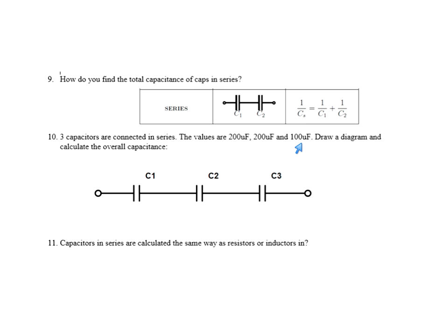But look at this. Here's how I would think about this. C1 and C2 are in series with each other, and they're both 200. If you do those two capacitors in series, that would give you 100. Two 200 microfarad caps in series would be 100. So these together are 100. Then you have another one in series with it, which is 100. So 100 in series with 100 gives you 50. So capacitors in series are calculated the same way as resistors in parallel.